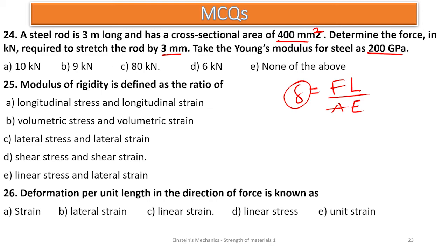But before we get the elongation produced, we can say the strain. We can use the strain to find the elongation produced. So strain is giving us elongation on what? The length. Or we can also use the formula stress is proportional or equal to E on what? That. And we can use all parameters given to solve for our parameters.